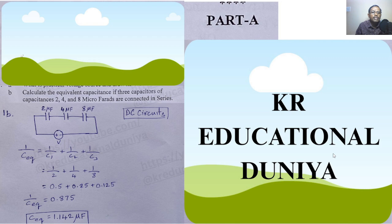So C1 value is 2 microfarads. So 1 by 2 plus 1 by 4 plus 1 by 8. At last we got 1 by C equivalent equal to 0.875 microfarads. I need the C equivalent value, that is the total capacitance value. So C equivalent equals 1 by 0.875. If you calculate 1 by 0.875, you get 1.142 microfarads. So this is the answer.